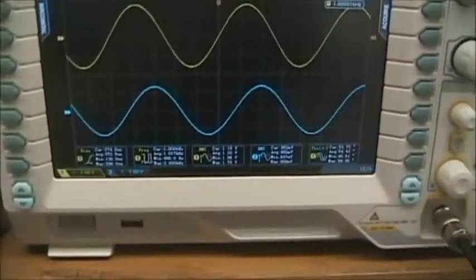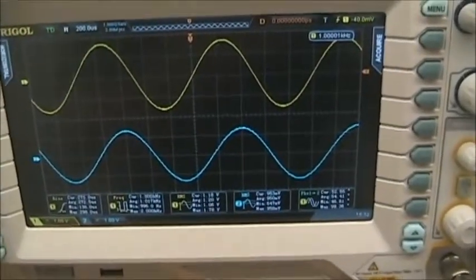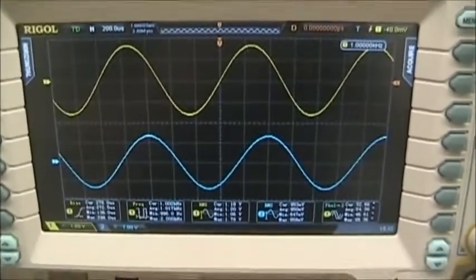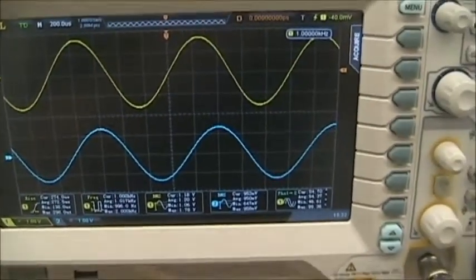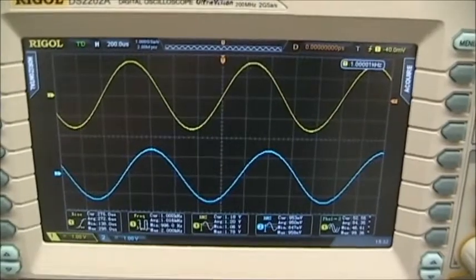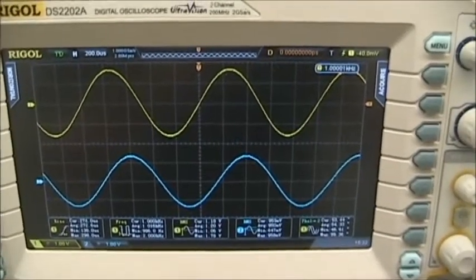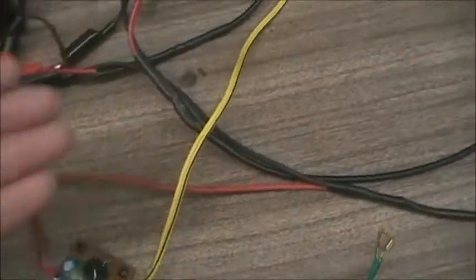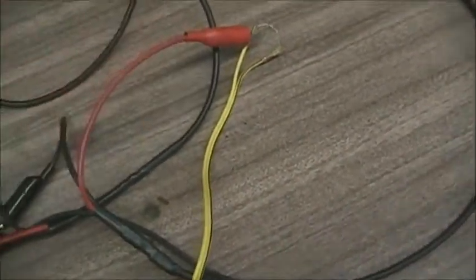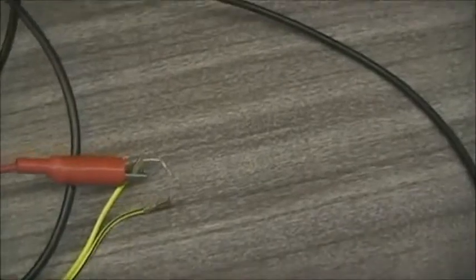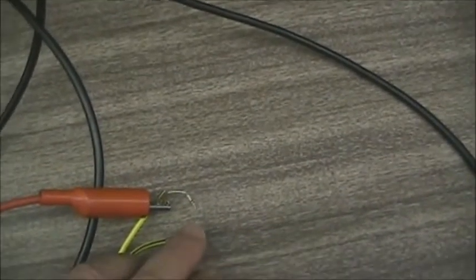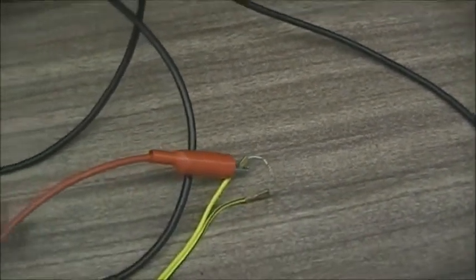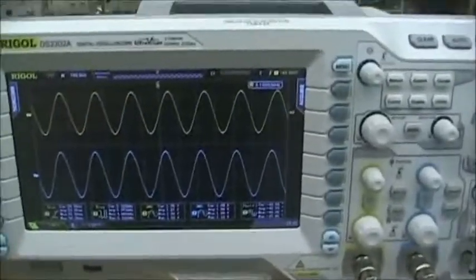Now, where do we start data-wise? Well, on a filter, it's always useful to start at a known frequency. So let's set up for measuring the high-pass filter and the critical frequency. Okay, so I'm measuring on the yellow wires, which is the high-pass filter. Don't forget the resistor, which serves as the load. Filters always need loads. And this is the display.